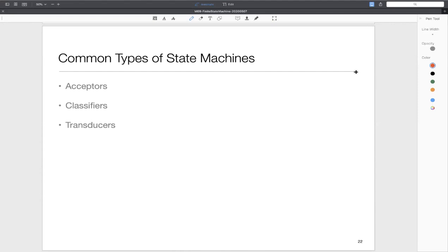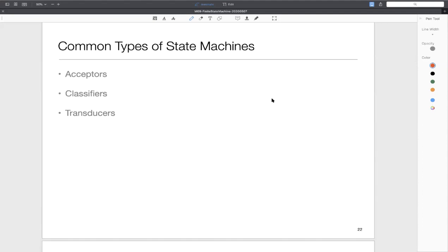Okay, so last time at the end of the Wednesday lecture, we had started looking at different types of finite state machines. So if you recall, in the last lecture, we had talked about how the hardware view of sequential systems corresponds to a graph where the different state vectors which are possible, so different bit patterns that reside in the state vector, correspond to the nodes in a graph.